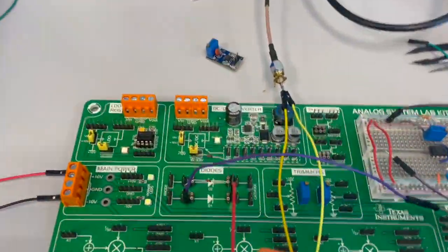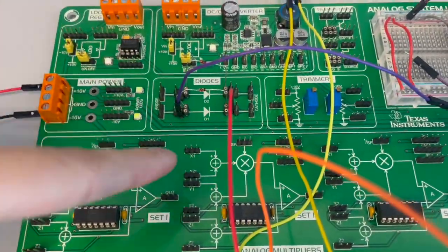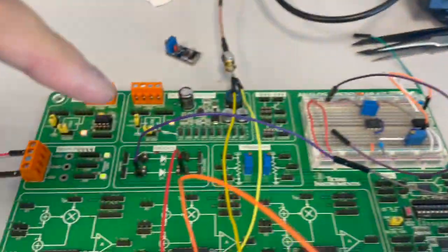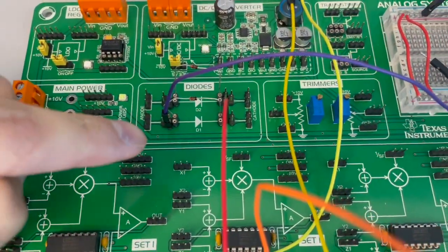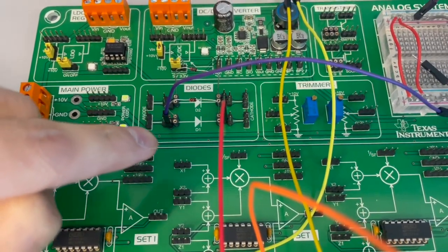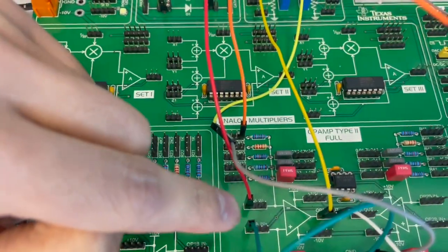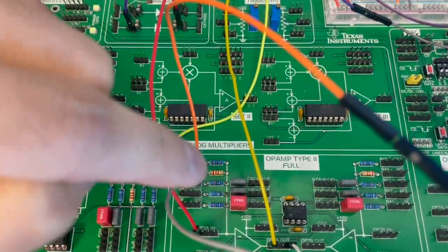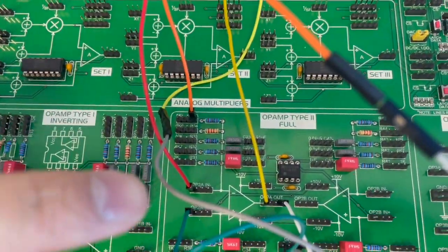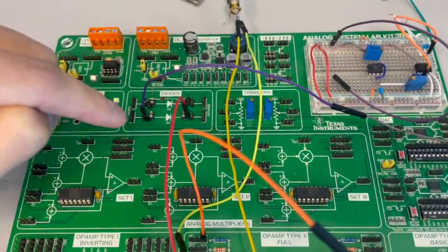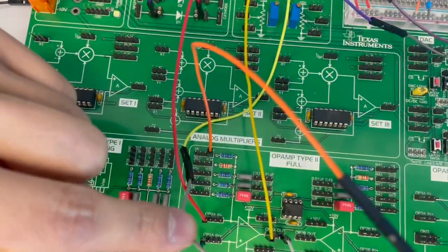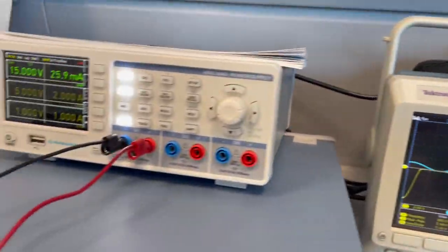Structure is the same, but we just need to swap. So this time the diode goes to the input, so the signal from the signal generator goes directly to the anode side or positive side of the diode, and then it goes to the negative input of the amplifier, and as a feedback we're gonna have 1K resistor. So 1K resistor feedback, and for input from the signal generator we're connecting the diode. Signal generator, the biasing is the same.